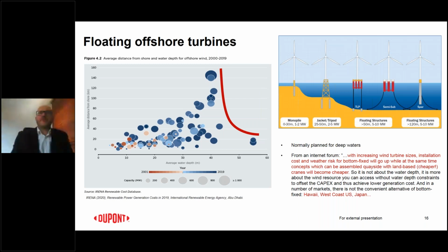While when developing the offshore systems, what was realized was that all these works, or the majority of works for assembling the components like the turbine or even the collector substation, could be done in the harbor. So there is no need for the weather window. There is no need for specialized crews and equipment to work far offshore.